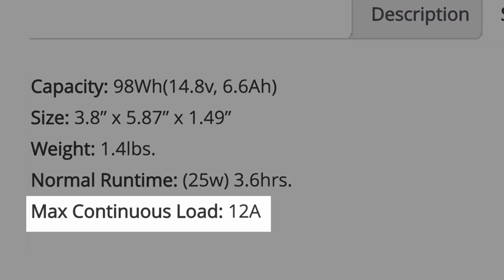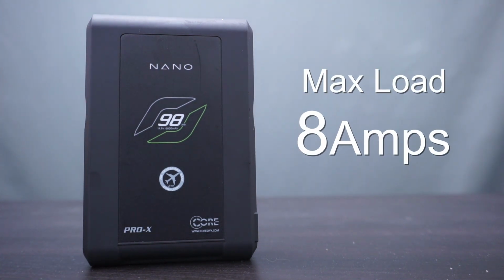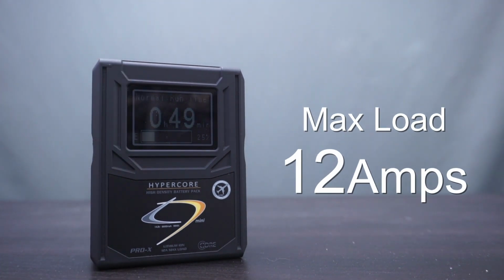But let's say your rig has a startup current or load amperage requirement of 9 amps with some really beefy lens motors. Which pack do you choose? On our site, each pack is rated for a maximum load handling. A Nano 98, for instance, has a maximum load output of 8 amps, so it wouldn't be sufficient for this rig. Yet a Hypercore or a Helix pack in a 98 watt hour capacity has a maximum load handling rating of 12 amps. Plenty of deliverable power available for the rig.